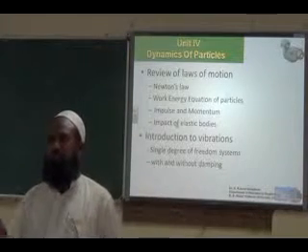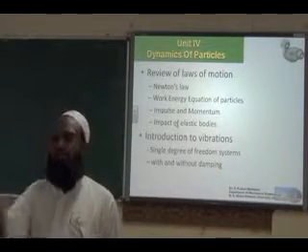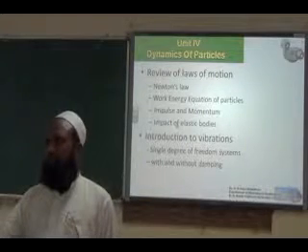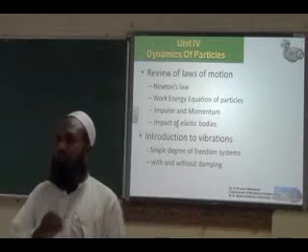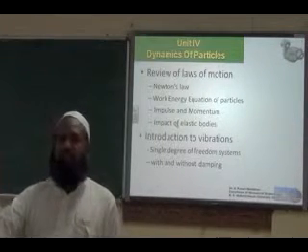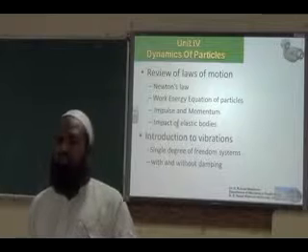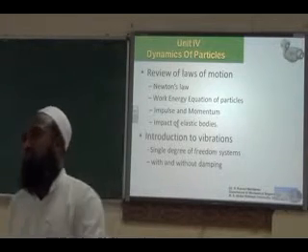What do you mean by single degree freedom system? You need only one parameter to define its position. The system is like that. It can be displaced in theta angle or in x direction. Like that, it displaces only in one direction. So such a kind of systems, we call them single degree freedom system.